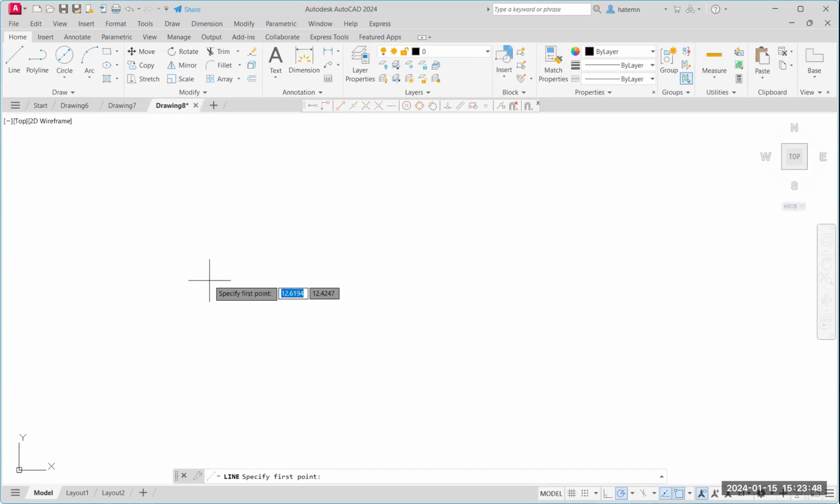So when you first open up a drawing, your 0, 0 is located down here at your XY. And you could use what's called absolute coordinates, which is what you learned back in high school and middle school, that if this is 0, 0 and I move over 1 inch, up 1 inch, over 1 inch, up 1 inch, and so forth, it's all relative to this absolute coordinate system. But we don't use that a lot in AutoCAD when we're drawing, because wherever we choose, we can actually temporarily make it a 0, 0 coordinate if we need to. So we're just going to draw somewhere on your screen, and you can follow along with me on here, or you can watch this video and then try some of these techniques on your own.